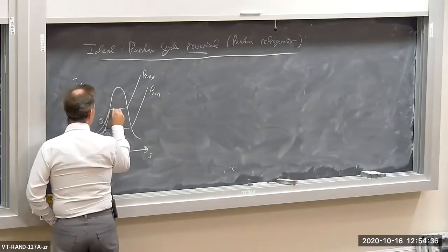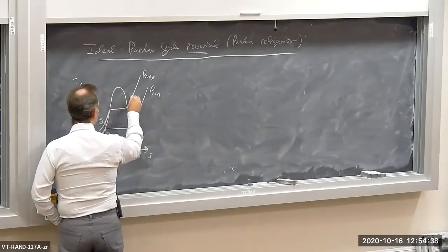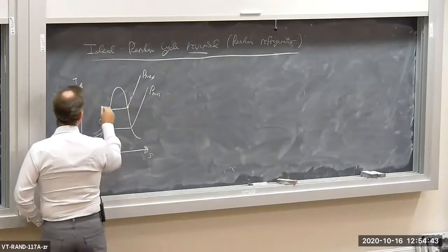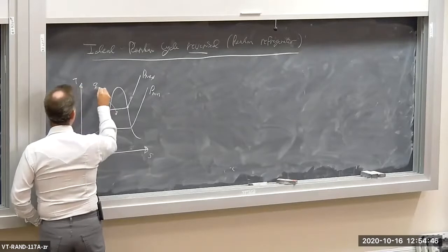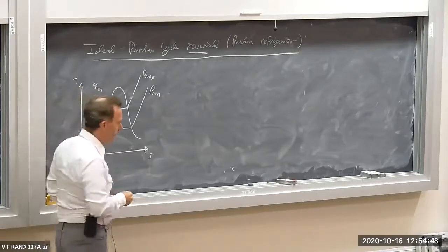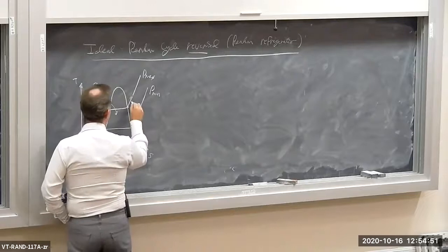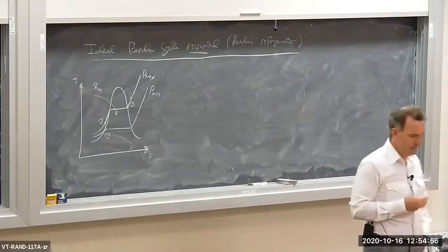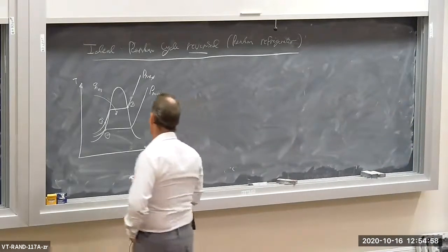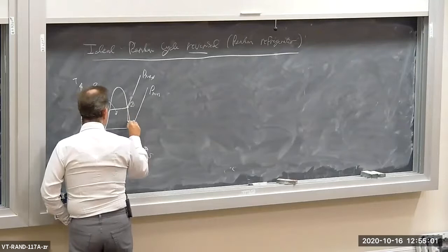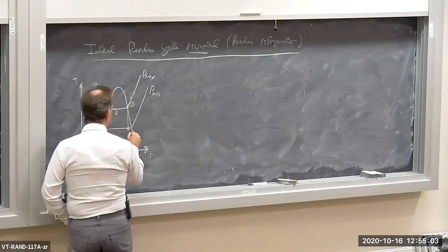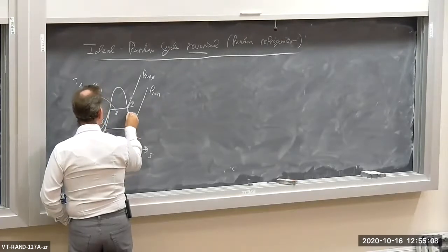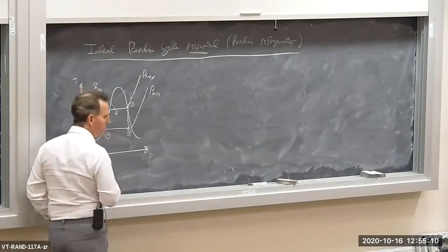And then, of course, we add heat. So here, this is an ideal cycle. So we're adding heat here in the boiler, Q in the boiler. State 3 is a saturated vapor at the maximum pressure. This is the ideal Rankine cycle. And then, of course, we expand isentropically, reversibly, adiabatically expand the working fluid in a turbine. So there's no heat transfer going on here and no heat transfer going on in the pump.